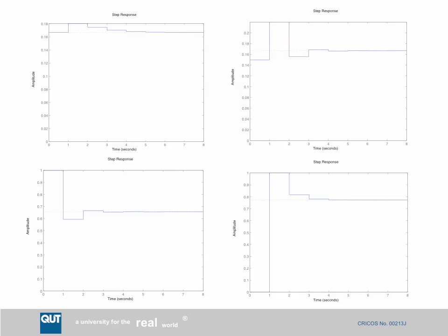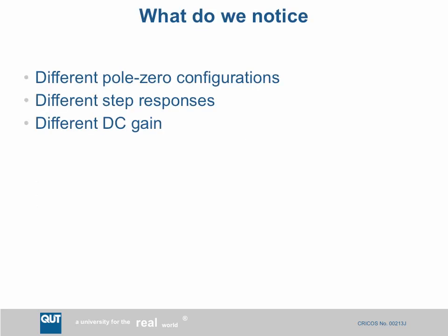Now, this system has been sampled rather slowly. We can see that it's showing a peak in just 2 or 3 time steps. We'll talk in a future lecture about how we choose the sample rate, but generally good practice is that you have anywhere between 10 and 30 time steps in order to reach the peak in the time response of your system. So we could say here that our sample rate is certainly far too low. We should be sampling much faster. And as we sample faster, the difference between these different types of discretizations will also become less. So this is a rather extreme example.